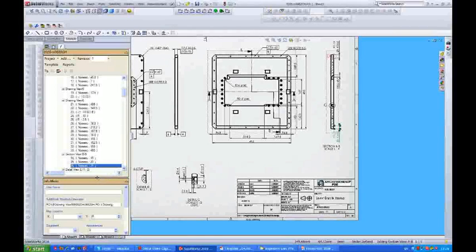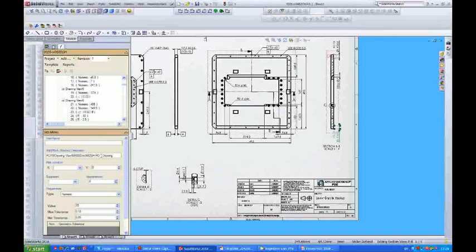Every dimension has an info area. In this info area, we have the dimension's internal SolidWorks ID. This is our connection to the drawing, and later on we can also upgrade to a different release by giving the same numbers to the same dimension ID inside SolidWorks. You can define here the equipment that you're going to measure the part with, and you can influence the general tolerance.